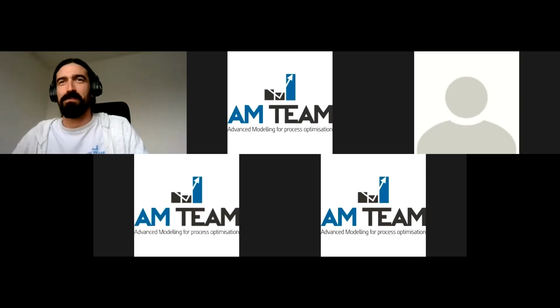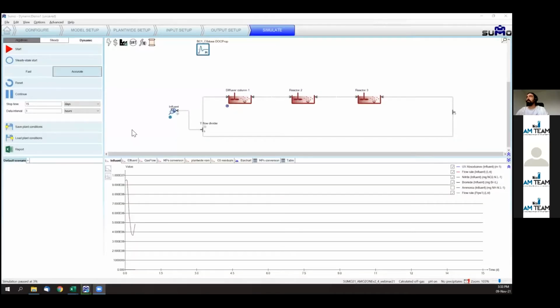Thank you. Let me share my screen and I'll bring you to my laptop, in which you can see a full-scale installation represented with a general injection system here. That can be diffusers, can be side stream injection or hybrid systems. And then you have the flow going through a couple of reactors. This is an installation of a total 100 cubic meters. And then there is an influent going in, which we can run dynamically, with a couple of days of dry weather, and then a rain event that will hit the plant in the 3rd day.